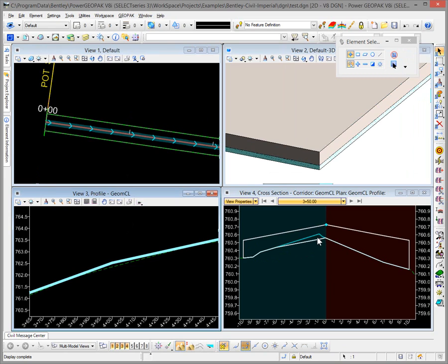And then the reason this milling goes below ground is because you've set a depth below component of 2 inches in your template, and so it follows that component as expected. And so you have a section here of actual milling, but over here there is no milling. Your leveling binder is just going to your existing ground. So that's one method of profile adjustment design. So let's do another one here. Take a look.